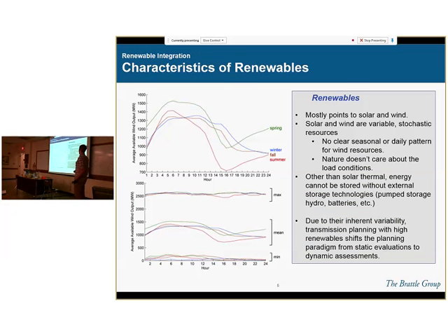So as you may know, the wind and the sun don't operate by our will. They are natural forces and are variable and intermittent. So I'm showing here on the left the average wind output in megawatts for each hour of a particular year in each season. So this is averaged for each hour in the season. And then in the bottom, this is the same, the lines in the middle here are the mean, and then the max and the min value here. So you can see there's huge variability in the output of the wind farm.